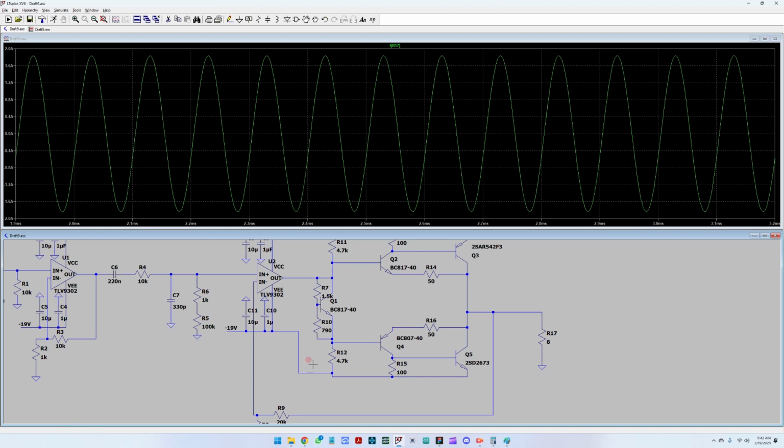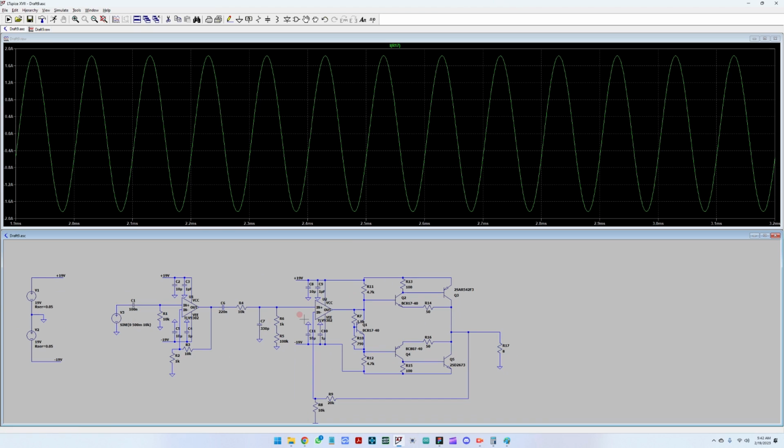By the way, when we are going to design this circuit, when we're going to choose the power supply, we need a power supply that can double this current. So it will be about 1.7 amps times 2, that would be 3.4 amps. Maybe we're going to go with a 4 amp power supply just to be on the safe side for the 19 volt supply.